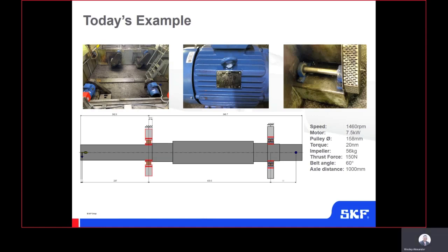Also, most importantly, we want to ascertain if using a roller bearing over ball bearings will be sufficient in terms of meeting the minimum load. So this is a self-aligning system, and we want to ensure that the minimum load on the roller bearing is met. If the minimum load is not met, this bearing could suffer from premature failure, for example, just one of the things.